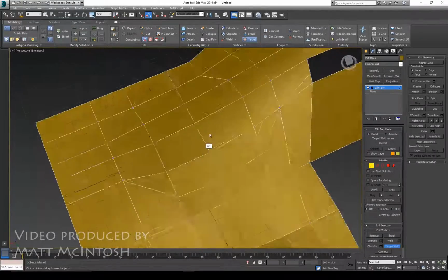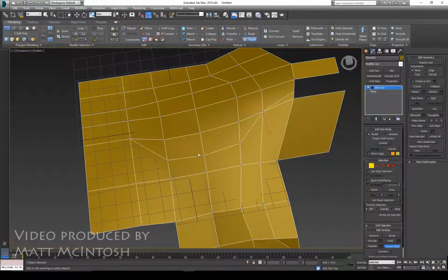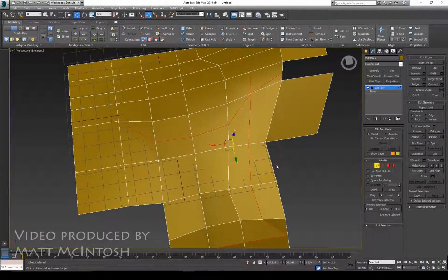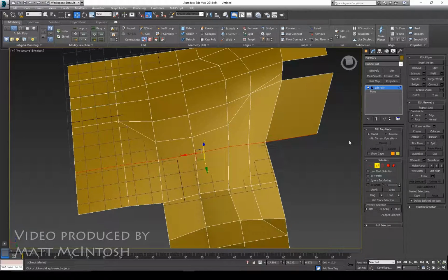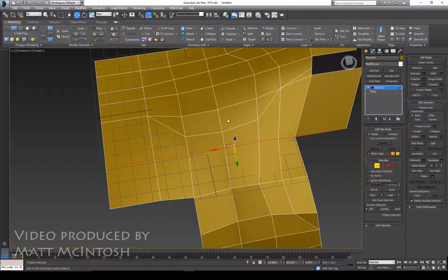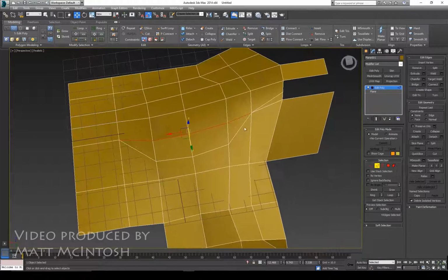Now, another aspect that things will have an impact on is if you start incorporating lots of triangles into your scene. If you've got quads, which are four-sided objects, or four-sided faces even, you can double click on your span and it will select the entire lot for you. If you've got triangles in there, what happens is the computer doesn't know which direction you want to carry on with, so it will stop at the point that you've got the triangles. So make your life a little bit easier and try and stick to quads, and only transfer over to triangles when you're happy with the overall mesh.